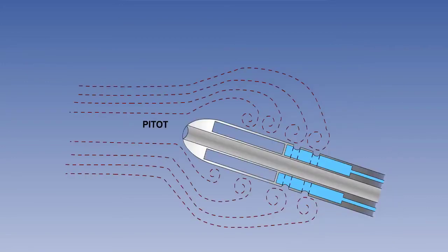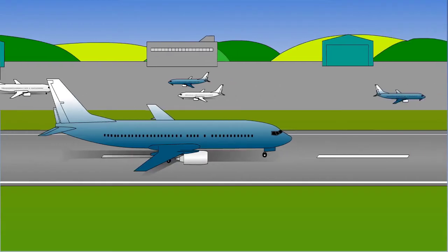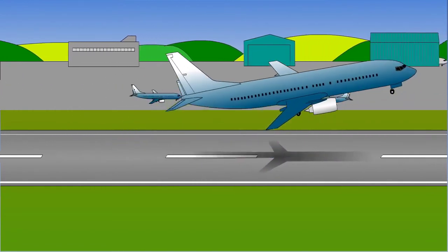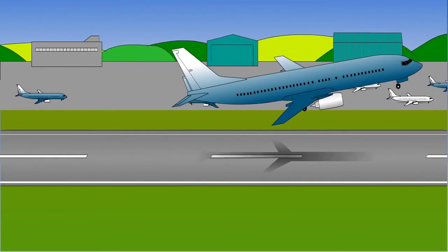The second error we will consider is maneuver-induced error. This error results mainly from temporary fluctuations of air pressure at the static vents, caused in particular by changes in the aircraft's angle of attack or when the flaps are activated. The error is usually most significant during pitch changes, such as at the start of a climb or levelling off and descending.